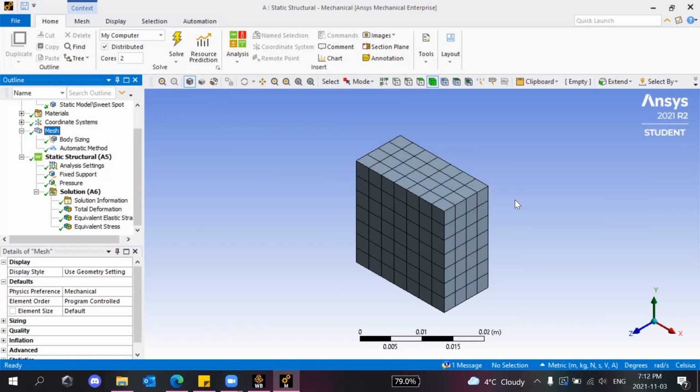Some teams couldn't create a mesh on their glider for some reason, and one of the common reasons was that some people would just leave a floating line or a floating surface somewhere, and that would completely ruin the geometry, and it would be so tiny that they wouldn't even notice. So that's why it's important to check your geometry, make sure it is suitable for simulations before you actually get to the step, or you might be going back and forth over and over.